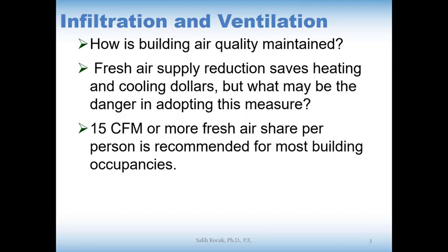Each minute, 15 cubic feet volume of fresh air or more per person is recommended for most building occupancies. So per person we have to provide at least 15 cubic feet per minute of fresh air to the space so that the air quality will be maintained.